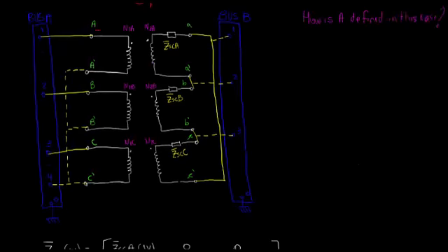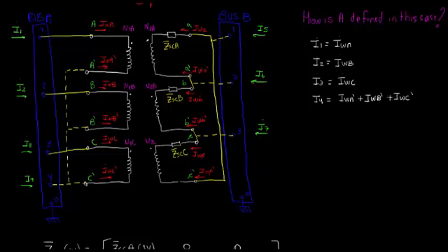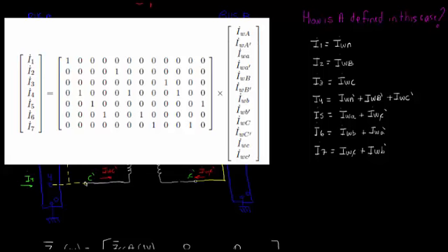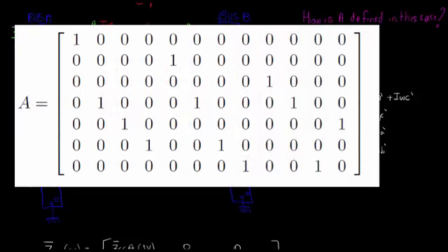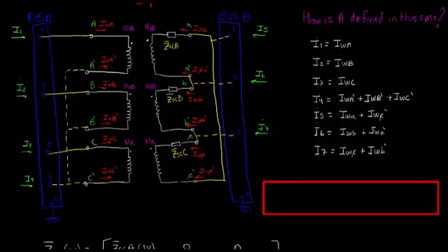Now, matrix A can be written by looking at the relation between the currents injected in each winding, in red, and the currents injected in each node of each bus, in green. One can easily find the following relations, which can be written in matrix form, like this. Then, the matrix A, in this case, is the following. With the matrices ZSC, B, N, and A, the Y primitive matrix can be calculated by using the same final expression we have used for the single-phase transformer.